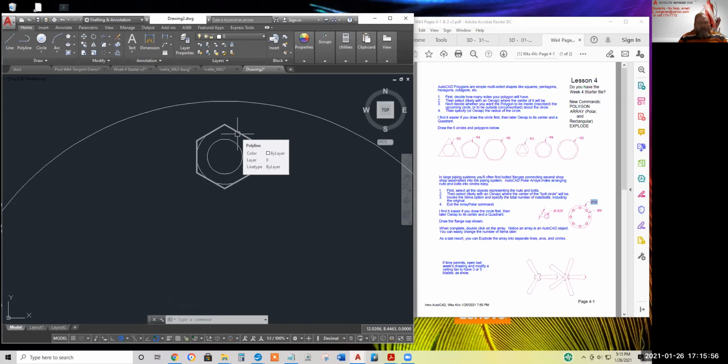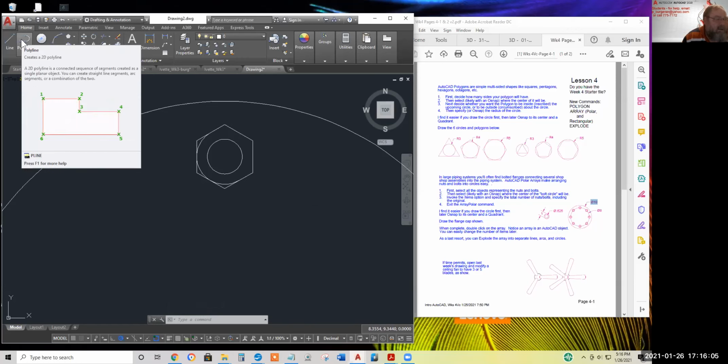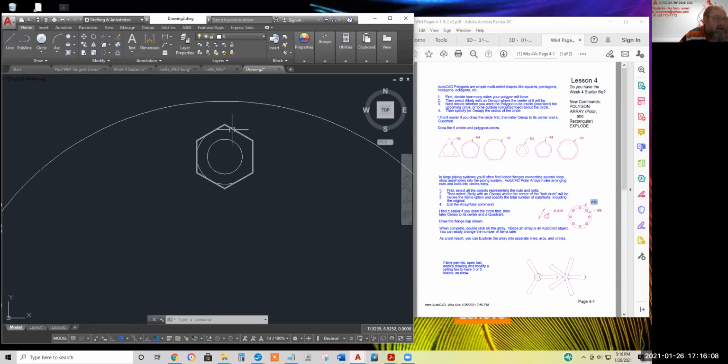I believe that's next week's material as well. Let me show you a polyline. A polyline is a high-tech item. Not as high-tech as a polar array, in my opinion, but check it out. A polyline, at first, looks just like regular lines going all over the place. Hit enter when you're done, but check it out. If I go to move it, I can select any piece of it. It's a single object with an extremely long list of XYZ coordinates for all these points. Hit enter to finish selecting the one object, and I can move it.